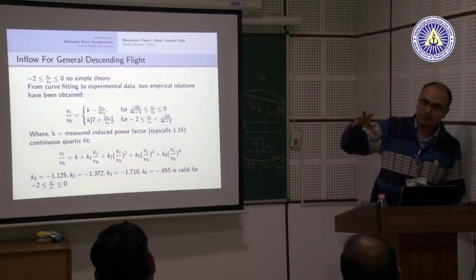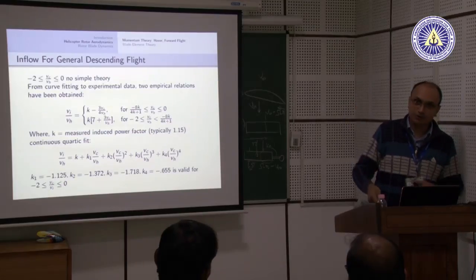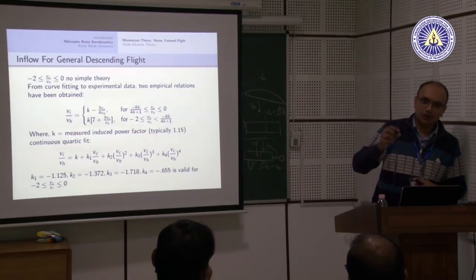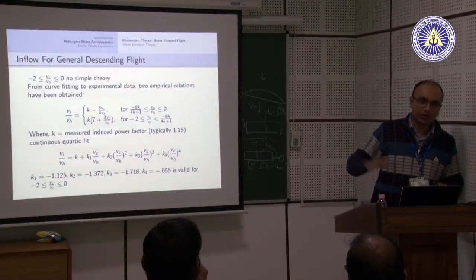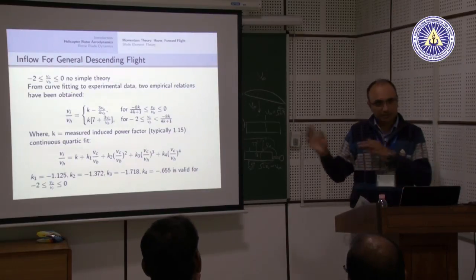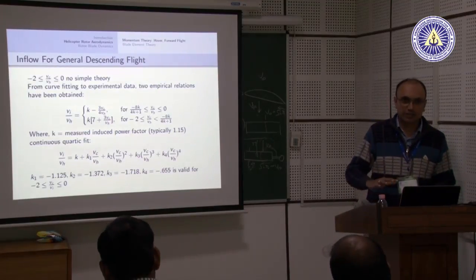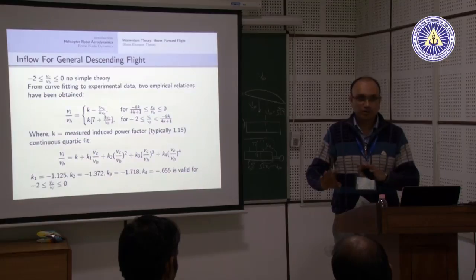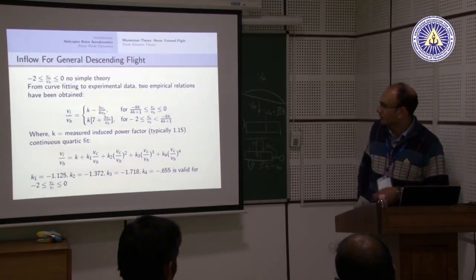So in those, they have built into the controller the capability that whenever you make it come down, it will always come down at very, very slow speeds. It is limited, you cannot make it come faster than that, and that is based on this problem of vortex ring state. If it comes any faster than that, it will actually lose control. Lose control means nothing can be done at all, because the aerodynamics is such.